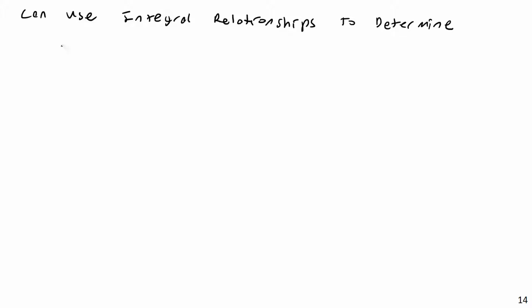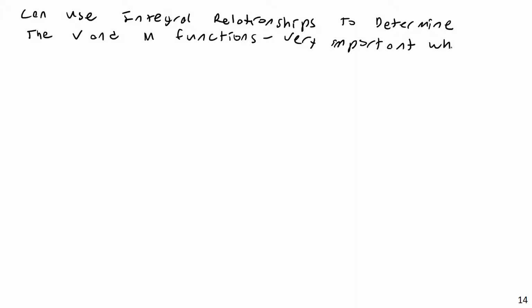But so what can you use this for? So that's nice, but what is this beyond trivia? Well, you can use integral relationships to determine the shear and moment functions, to determine the V and M functions. And this is especially important, very important, when, let's say, the load is complex.